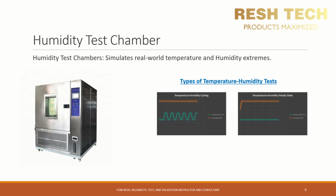Let's go ahead and take a look at two examples of high temperature, high humidity testing. The first graph demonstrates a high temperature and high humidity cycling test. As you can see, the humidity is held constant in the graph profile. However, most test standards that cover temperature humidity cycling allow for a certain percentage of tolerance for humidity drop, as the relative humidity will most certainly drop to some extent as the temperature is decreased in the chamber.